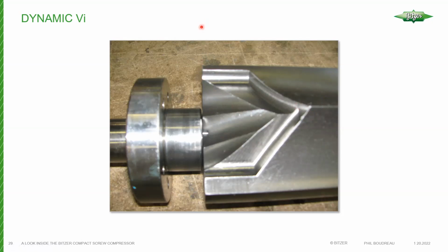And then on the pressure flange I mentioned before, your discharge port is on the discharge flange itself. So the slide valve moves into the discharge flange, and this port gets smaller as the slide valve moves towards it. Due to this, you can see that it gets larger as we get towards the center of the slide valve.